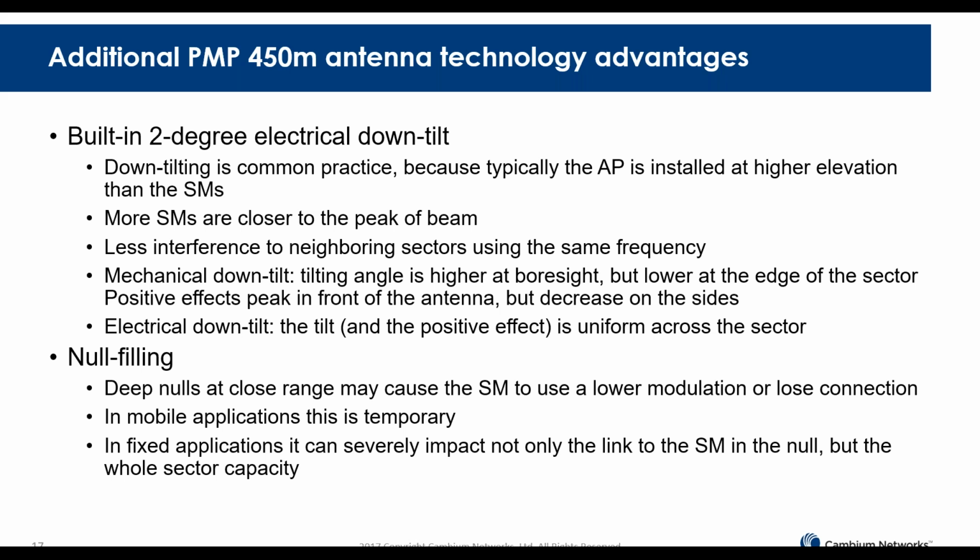The truth is that everybody benefits from these improvements in the antenna design because these subscribers in these locations that have a better experience can now transfer data at the higher modulation, which means that the access point is spending less time communicating with these devices and can move on quickly to other devices. All the devices in the sector experience a better throughput and the whole sector capacity is increased.